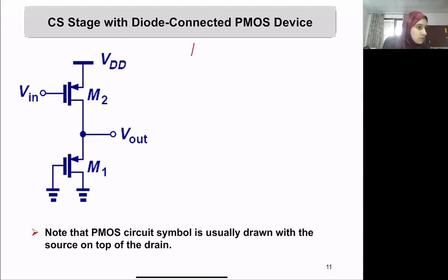Okay. So again, the gain is minus GM with GM1 or GM2. I look at where the input is applied. The input is applied at the gate of transistor M2, therefore it will be minus GM2. Now with the impedance of my M2, so it will be R out 2 looking up, and now in parallel with the impedance that I'm going to be seeing down. Which one down?